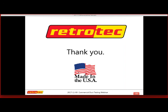Is there a maximum tubing length? Not that I'm aware of. The only thing you want to be concerned about is that it's not sagging and doesn't restrict your flow. If you're going to do something that's 20, 30, 40 feet, you're definitely going to have to support that at some point, and then run that into your duct. It's not a matter of just plugging it into your duct and letting it dangle for 40, 50 feet. You're definitely going to have some type of support at the top that's not crimping it, and then let that flow down.